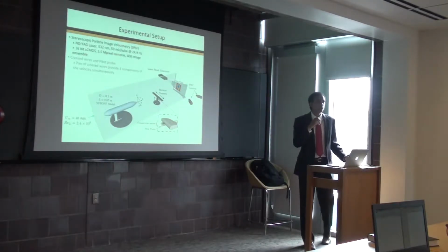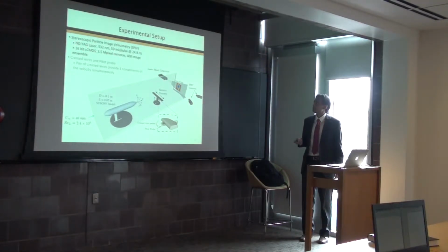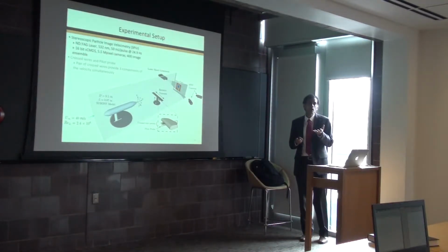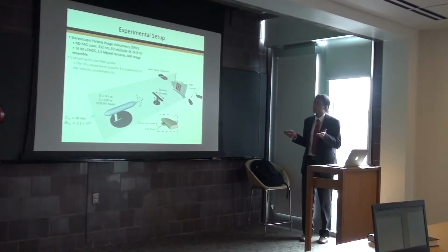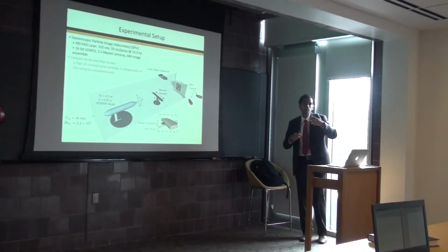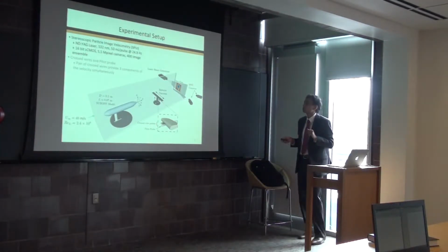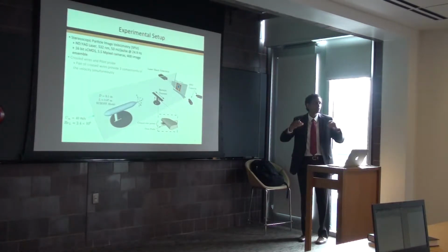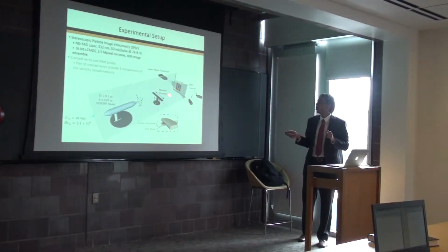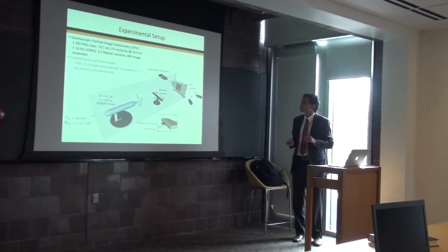That's quite a mouthful, but for some of you that's well known. For those that isn't, it's a technique that involves seeding the flow with tracer particles. These tracer particles are then illuminated using a light sheet. In this case, that light sheet is in the cross plane, because that's the plane in which we're going to see the footprint of those vortices that we saw in the flow visualization movies. And then we're going to image these with 2 cameras in stereoscopic configuration, which allows us to resolve all 3 components of the velocity at a single plane. And we'll do this for multiple planes.